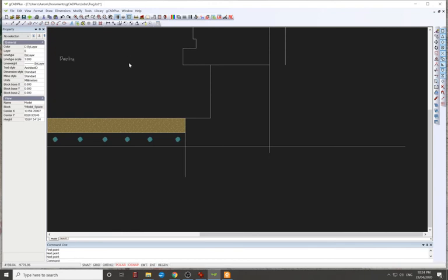So what I'm going to do is, where's that measurement? That was 3170. So draw a line. I should have just done this in the first place. 3170, and we're just looking for it to polar snap at 45, which is there. That's it.